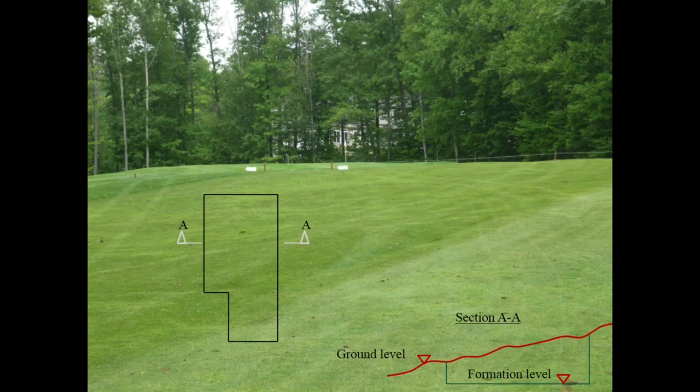So we cannot just apply that rule saying the volume is the area times the height, but here the volume would be the area times the average height, from the ground to the formation level.